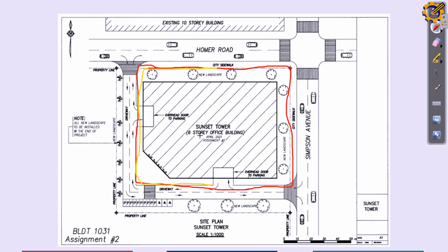For setback line. Imagine maybe in the next 15 or 20 years, the government wants to expand the road. It is going to affect some of your building. I'm not saying that if you follow the rule and have a setback for your building, it won't affect it. Even if it does, it will be maybe a small part. It won't affect a lot compared to somebody who says, I want to use up all my land, and moves the building very close to the edge of the land boundary.